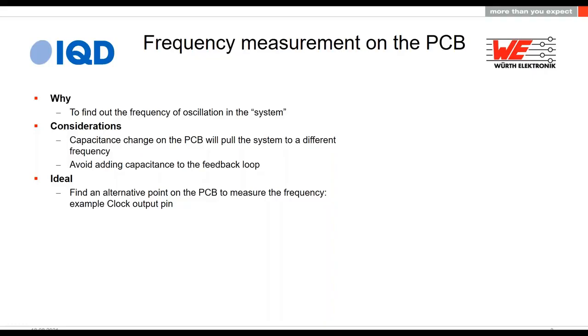When I was a kid and we were using microprocessors, they used to have a clock output pin. That was fantastic for doing this with. Nowadays, I have hardly ever seen that anymore. It's normally used as an I/O pin or something. You might have some software functionality that allows you to make one of your I/O pins into a clock output pin. If you do, fantastic. If you were asking me to do that work, I wouldn't have a clue how to program your system, and I wouldn't want to touch your firmware.